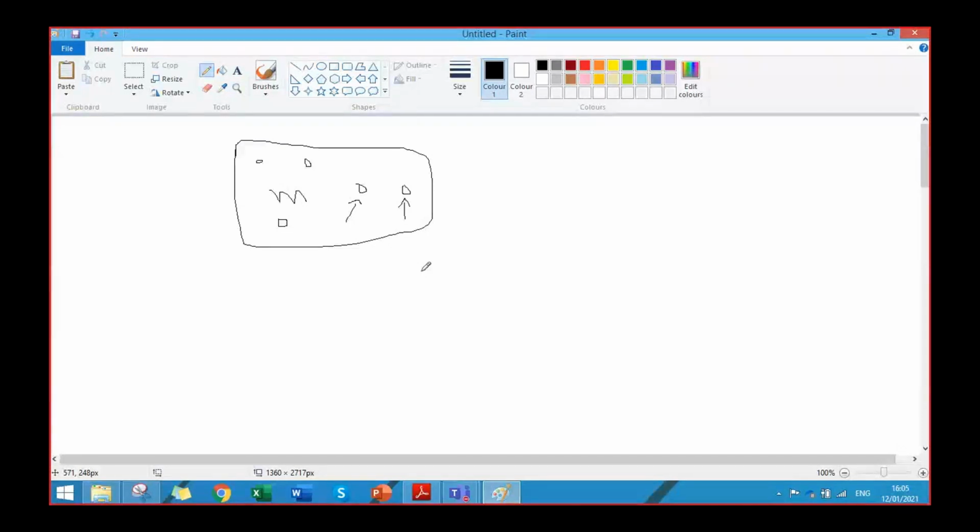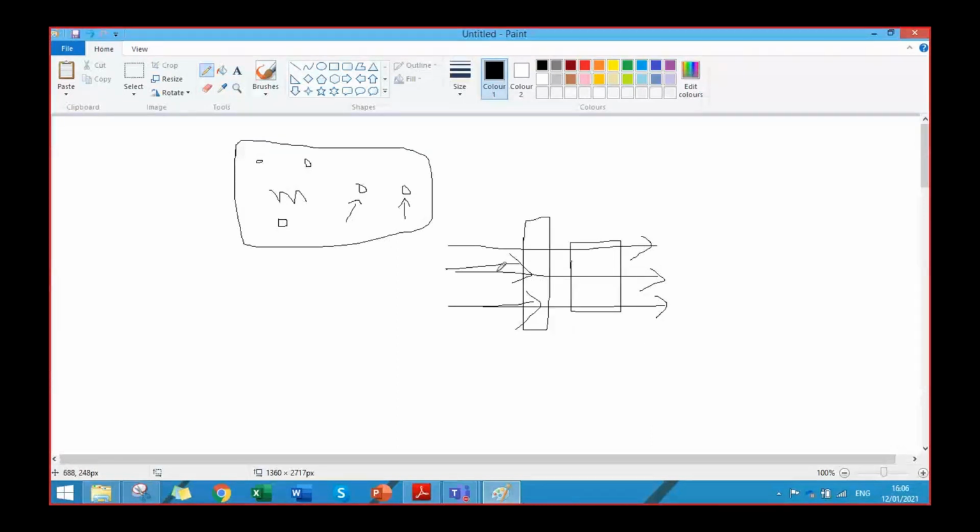Let's say this is a body and air is passing across it. We are interested in seeing the effect of the air passing over this body, the force that this air will exert on this body, right? Always there will be a different mass of air that will pass across this body, with different properties. So we cannot use the system approach. We cannot define, okay, we are taking this mass of the air and we'll see how it interacts with this. No, we are having fresh air every time.